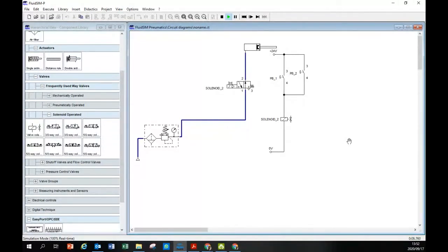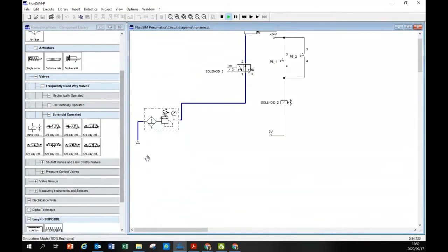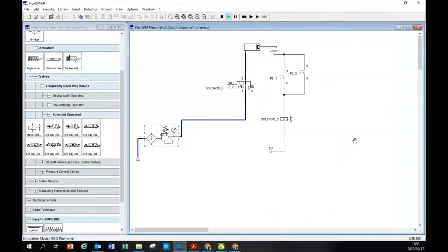Push button 1, push button 2. This is how we do the OR. I press this, it goes back. I release, it goes to the initial stage, initial location. I do that. Let me press. You see, it's connected through push button number 2. It goes to the solenoid. So both of them are connected to the solenoid. Both of them are connected to what? To the solenoid. Okay?